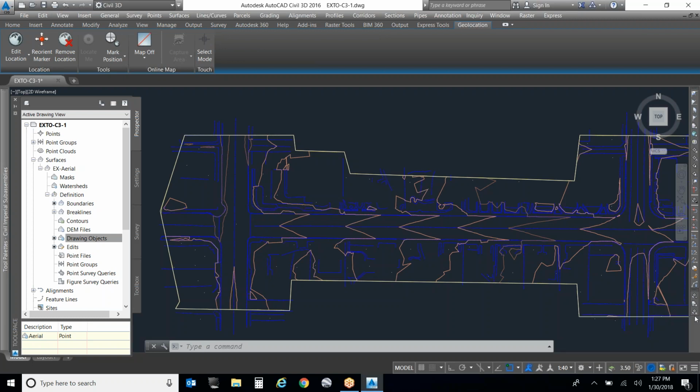Question. So surface files, the Civil 3D surface file, is heavy. My project manager asked for contour labels so that you can see what elevation the contours are. Where's the best place to put that surface so I can link it? So there's a couple different ways of doing that. Probably the lightest way is to create a standalone file, data shortcut your surface in, create your labels, right?